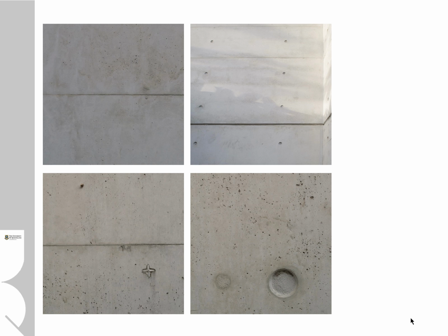Well, this is the same sort of thing but for a wall, and the plastic little chair makes sure that the mesh is held off the wall at a certain distance. And in this instance, the formwork, or maybe it was hit by the vibrator as it was being placed, has offset that plastic chair, and as a result it's actually blown through and is now visible on the outside of that surface. Again, not a lot you can do about that.